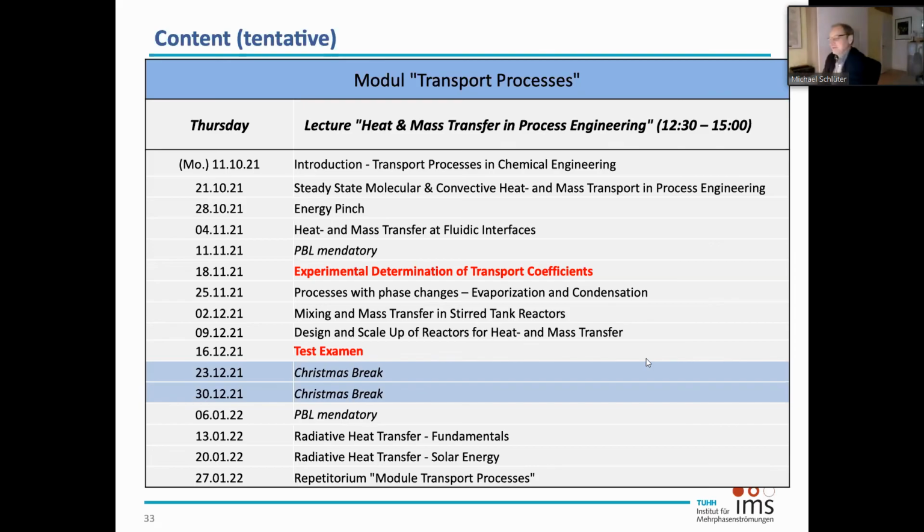But you need a material that sucks very strongly the liquid, and of course it depends on the liquid that you are using. Usually you use some refrigerants for this kind of application as well, not only water. But steel wool works as well. So it needs to be a material that sucks strongly the liquid phase and transports this downward again.